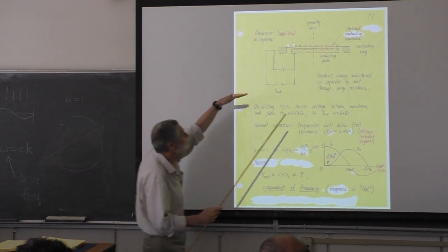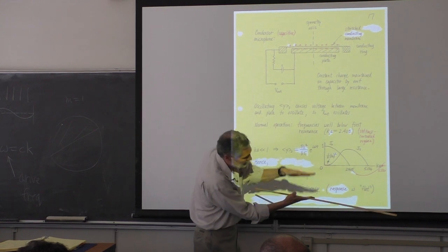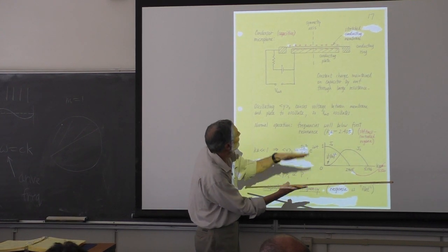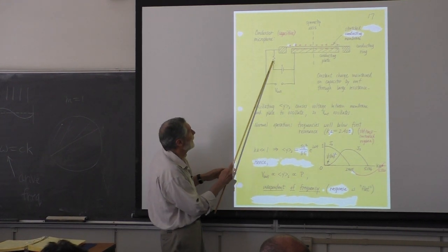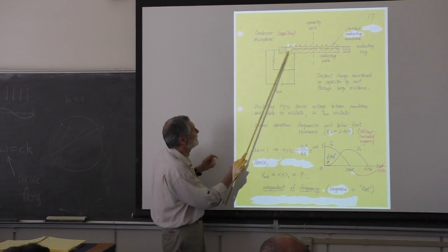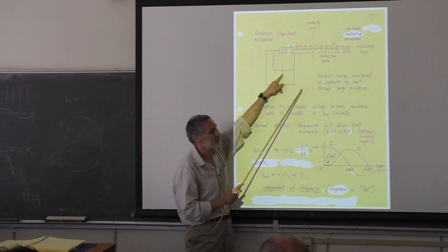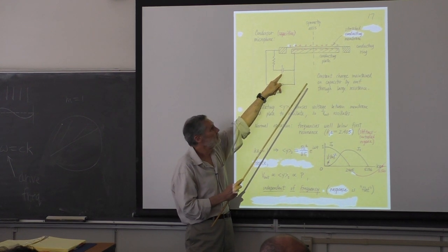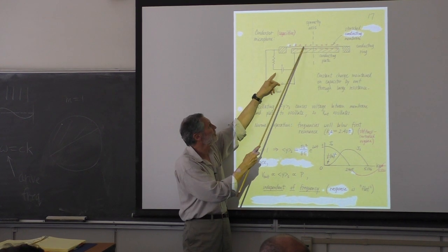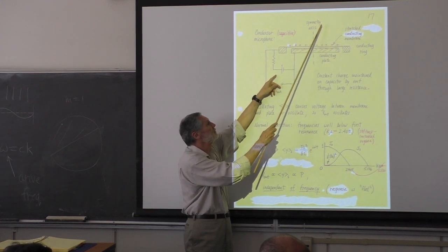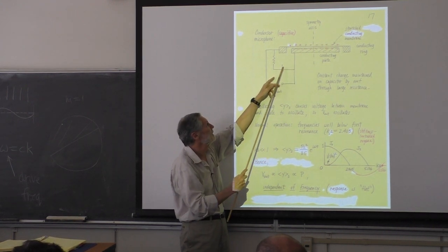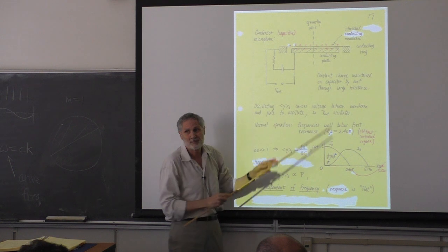So when this wave comes here, it's going to modulate the distance between the plates like this. We have this resistor big enough so there's not enough time to keep the voltage across here constant. That's what this thing wants to do. So its purpose is just to leak charge on there. As charge goes off, usually by humidity, as I described, this will keep it charged up.